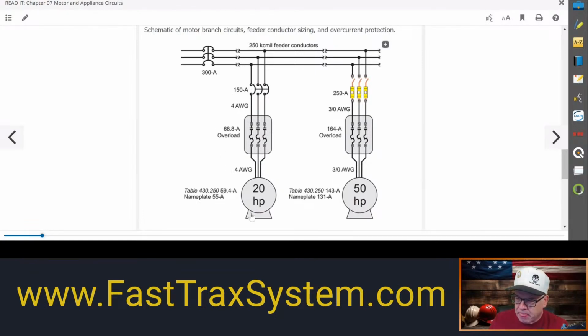And then we need to know what the motor's FLC is. When we see FLC, there's another slang term that we use, and that is FLA. And FLA, just think of that as the amps on the nameplate. FLA, think nameplate amps, versus FLC, which is what's in the NEC. Interesting about that is, why do we always use the FLC for most of the stuff, like the wire sizing and short circuit ground fault protection side? Why do we do that?